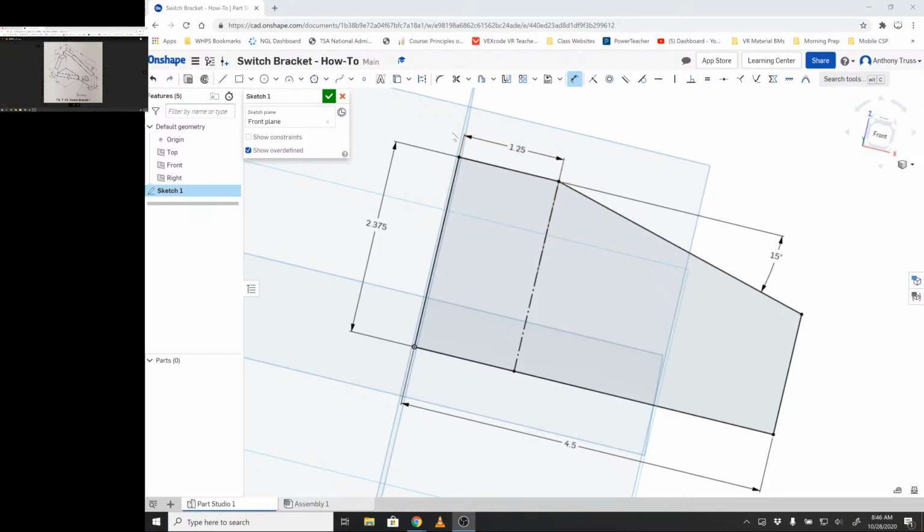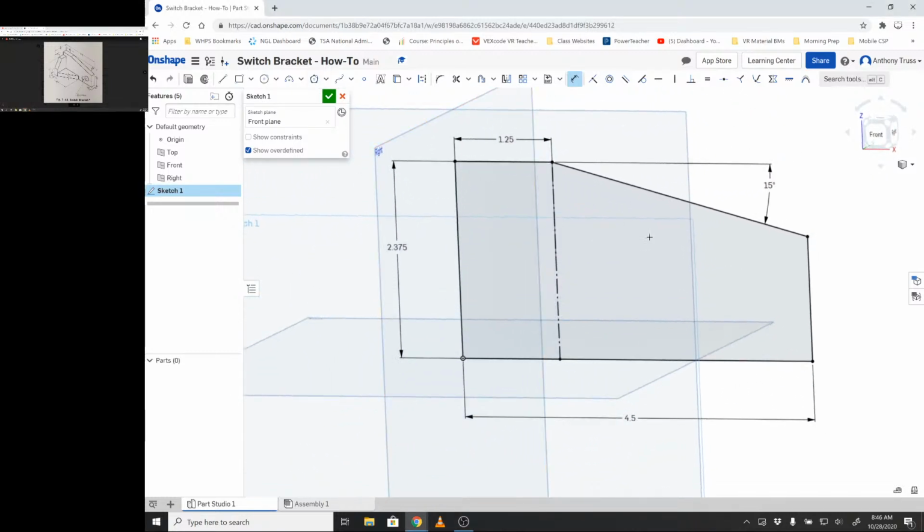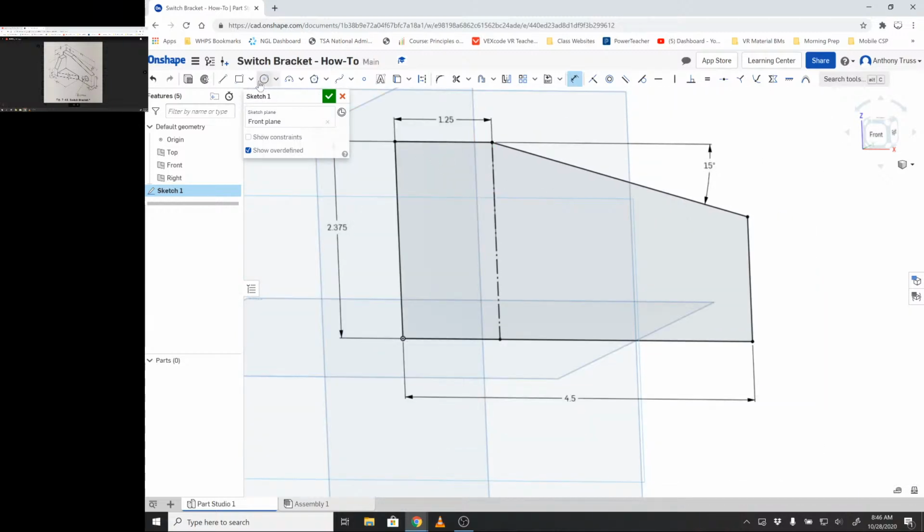Alright, so let's create that circle. We're over here on OnShape at this point, and we're going to use that information we just talked about, and we're going to create a circle from the center point, some location. It's obviously not in the right location, it's not the right size. So holes and circles typically need 3 measurements, the X and the Y, and then also the diameter. We're going to do the X first. We're going to click the edge of the part and the center of the circle. Unlike SolidWorks, you click the edge. With OnShape, you click the center to position from the center. To me, it makes a little bit more sense.